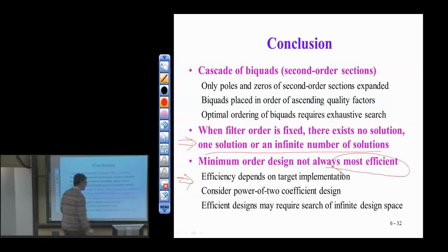Now, this may also be counterintuitive. But if you increase the order, you eventually can unlock some very interesting designs where all the feedback and feed-forward coefficients, or actually half of them, to be more fair, are power of 2 coefficients. So I don't get a lot of precision loss when I use them.